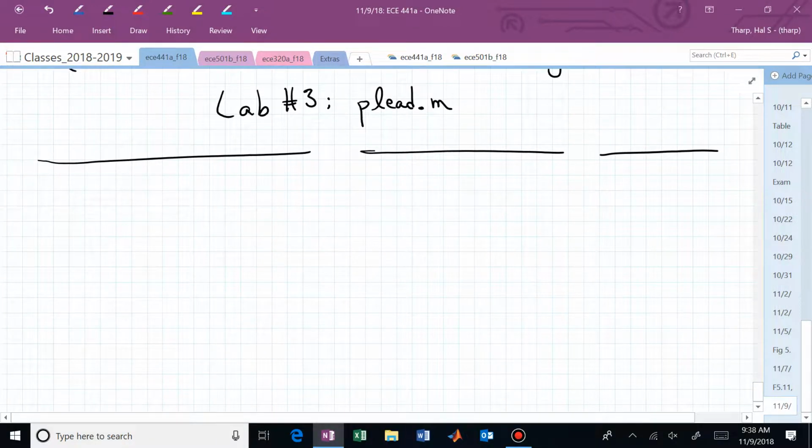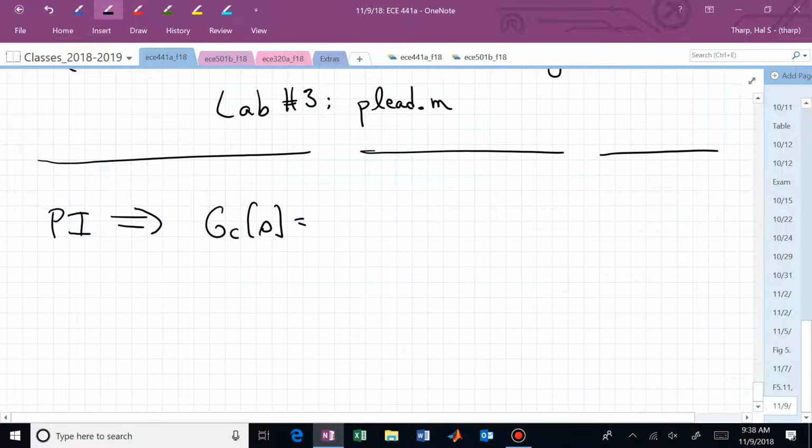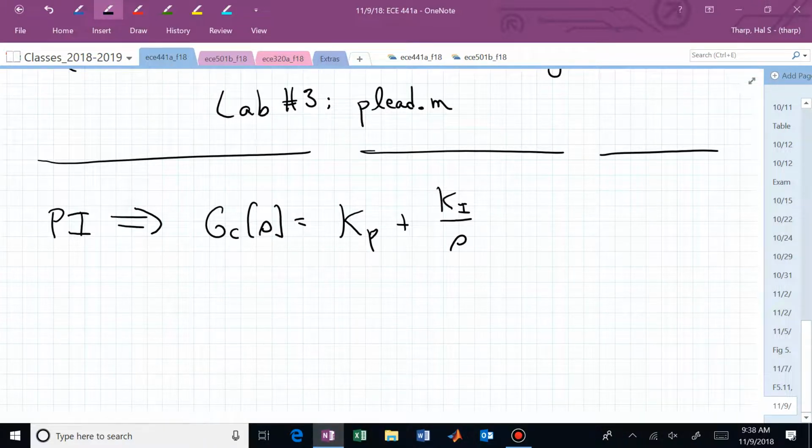What if somebody said, okay, I want to create a PI controller. G sub c, well, PI actually gives you a hint. That tells you what the controller looks like. It's a proportional piece and it's an integral piece. There's a PI controller. We're just adding up those 2 types of control actions. The proportional works with the present error. The integral works with previous errors to try to eliminate the error in your system.